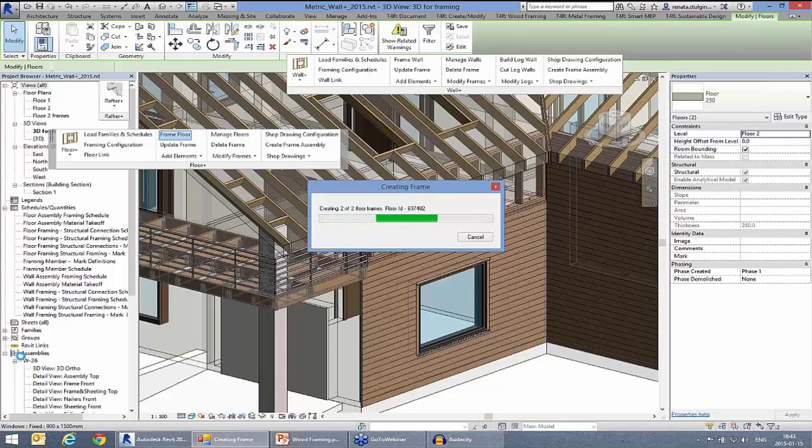For example, this assembly that we did for this wall has the name W26. This is the number from the wall, so this is a mark value from the wall. You have to be sure that your walls or floor panels are marked, because later that will be used in making shop drawings.